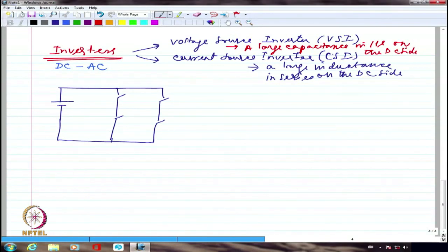So the two are dual of each other, basically, right? So if I am having a circuit like this, which is S1, let us say this is S4, this is S2, this is S3, and I connect the load here. In the full bridge DC-DC converter, we had connected the primary of the transformer winding there. That's all is the difference. Whereas here I am directly connecting the load, which will require the AC supply.